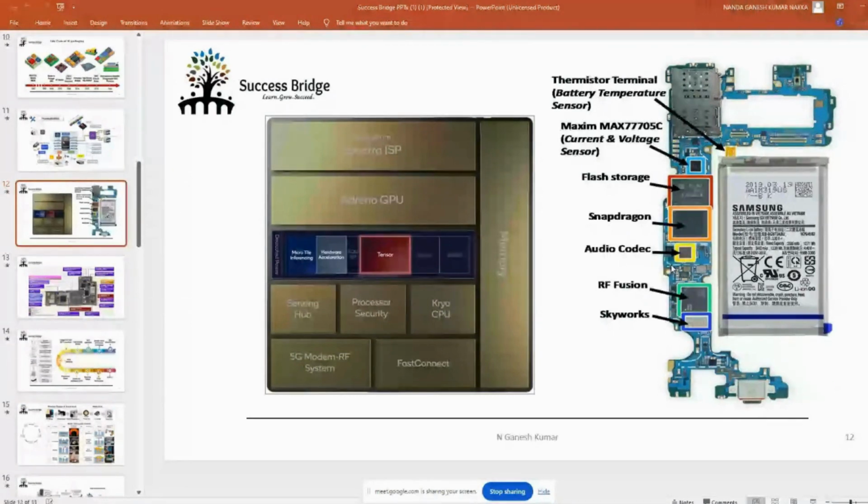To know that, this entire device, this particular Snapdragon IC, needs to be testable. Okay, if it is testable, then only you will be able to test it post manufacturing. Okay, so post manufacturing, if you want to debug, diagnose, or refurbish an IC, you need testability.